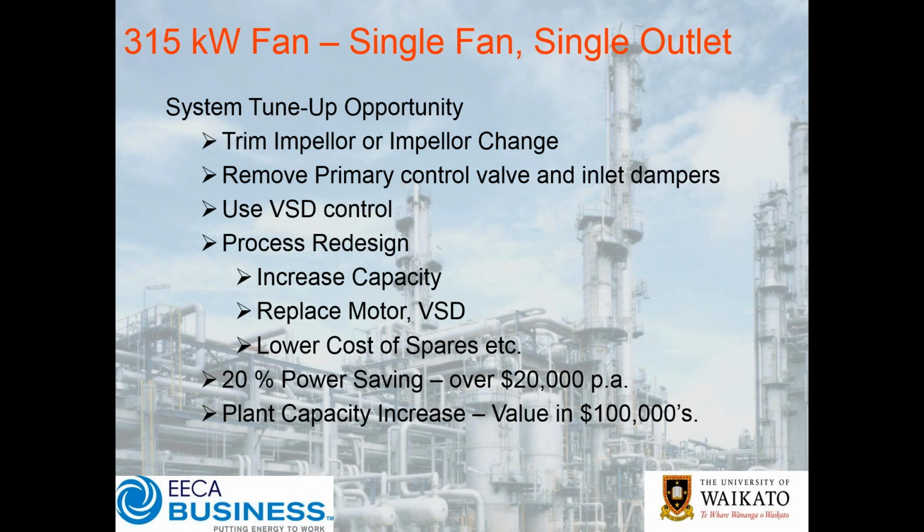There are other maintenance implications here. Now, of course, if you don't need a motor that big, obviously carrying a spare to be able to change out becomes very expensive. Likewise, VSDs and so forth. If you can consolidate, you might not go to the smallest motor available, but thinking about how you can consolidate and rationalise what you might need to keep in terms of spare parts could also be useful.